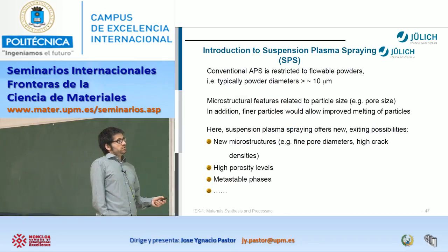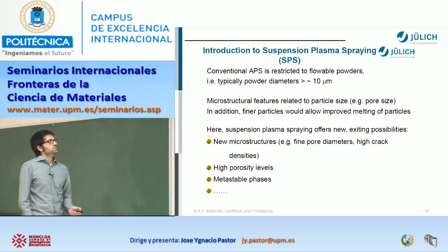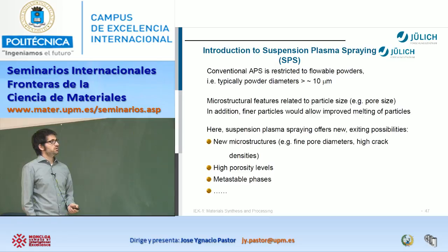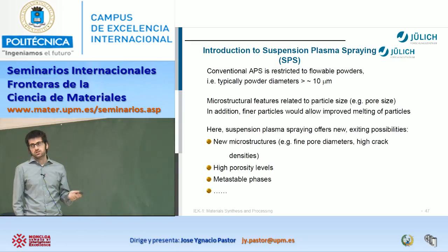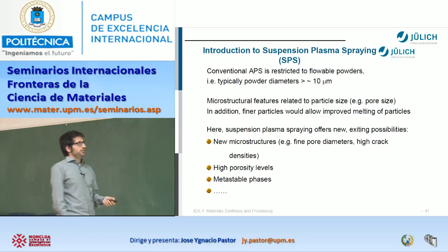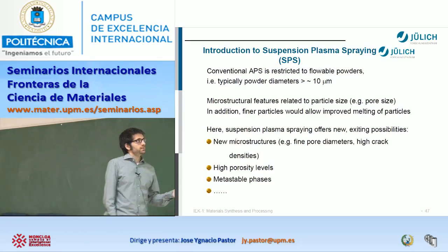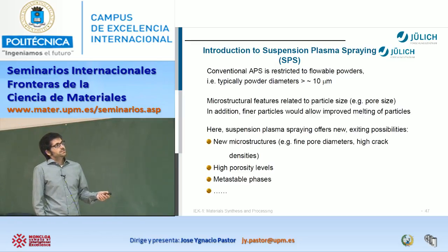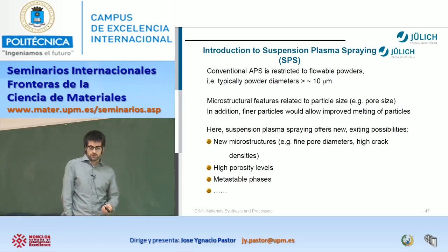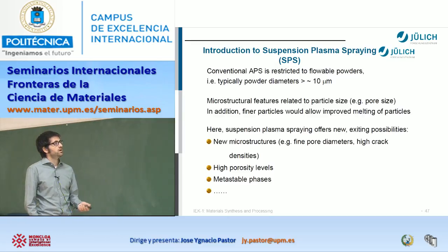And here, well, is one technology that we use so much in our center, which is suspension plasma spray. This is like the conventional APS, like a modification, and in that case, yeah, we introduce a suspension, because normally it's dry powder. And as I told you at the beginning, normally it should be dry powder. Your powder should have required inherent properties that not all the powders have, like flowability. For example, ceramics are really bad, metals are good, but ceramics are bad.